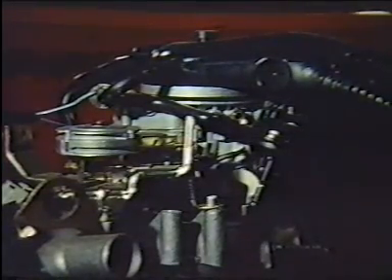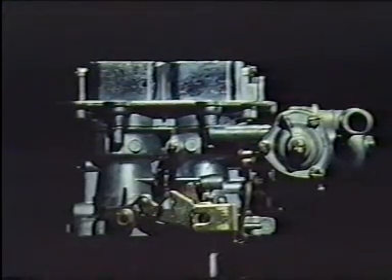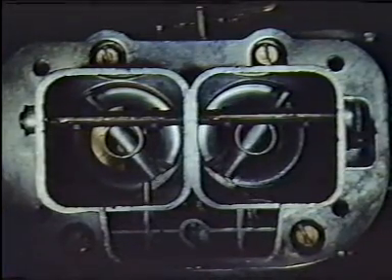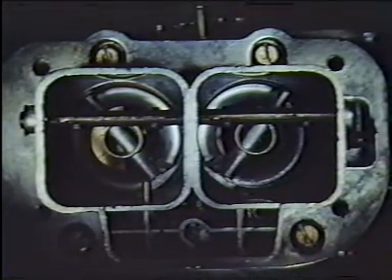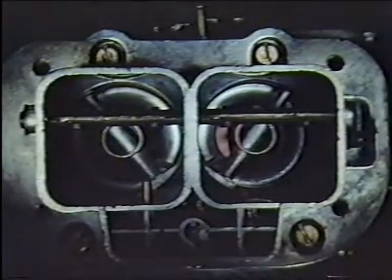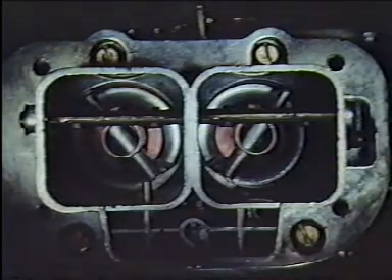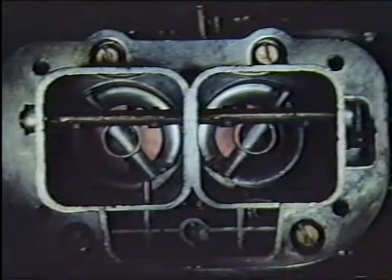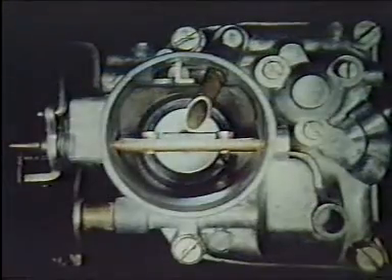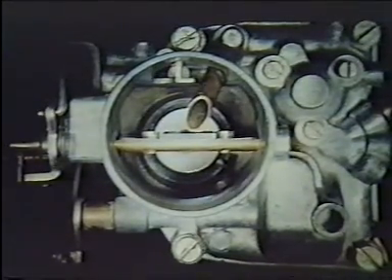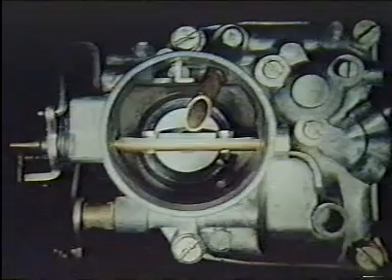One development which meets the need is the twin choke carburetor. It consists of two carburetors of different diameters side by side in the same casting. At lower revolutions, the needs of the engine are met by the smaller carburetor. At higher revolutions, the larger diameter carburetor comes into operation, greatly increasing the flow of mixture into the engine and improving its performance. The task is always the same. It is simply to deliver the right mixture of fuel and air to the engine at precisely the right moment.